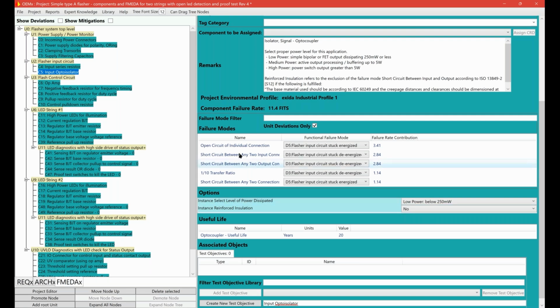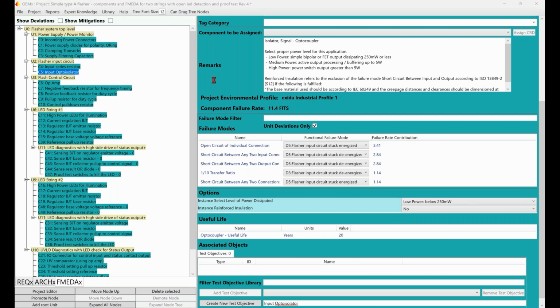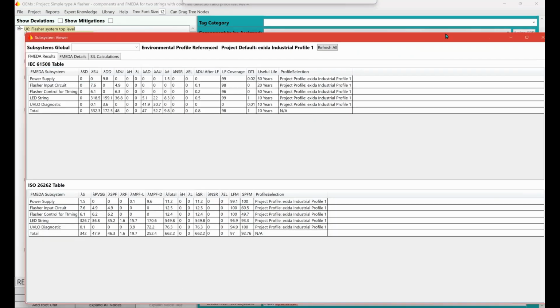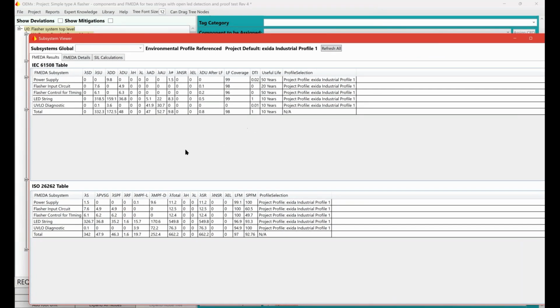And you can see overall that we can have a big effect. When I look at the FMEDA results, I just see what the totals are. My DU is down to 48. I'm glad of that. I have a very good latent fault test with pretty high coverage factors. I have a diagnostic test interval that ends up for the device as 1 second, worst case wins.